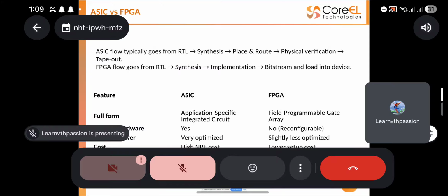So when you have an FPGA board, that board comprises all those resources. Whenever you do placement and routing, whatever code you have written, it will take the resources it needs from the available occupancy and do the placement and routing inside the hardware. That is the implementation. And once the implementation is done, you will do the bitstream generation.